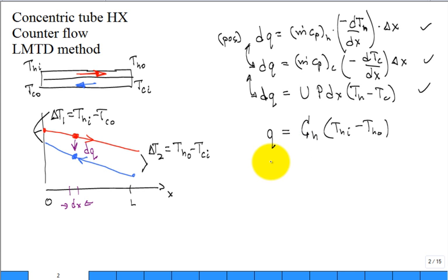All right, and then Q, the heat capacity rate of the cold fluid times the temperature, and this is where I have to go slow. I have the cold temperature fluid, but which one's higher? I want a positive Q, so I better put the temperature cold out minus temperature cold in. Do you see that? They just switch locations. Which one goes first? You always want to talk about a positive Q. And the Q is positive out of the hot, and it's positive into the cold.